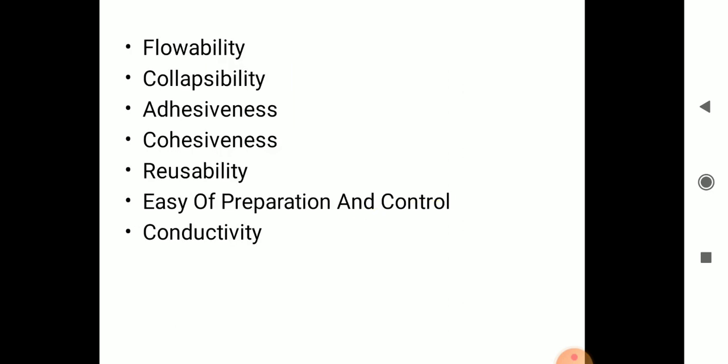Next is flowability. The sand should pack well and flow under load. Sand of low flowability may result in non-uniform hardness, soft mold, enlargement of the casting or roughness of the casting surface. This is flowability. Next one is collapsibility. The molding sand should also have collapsibility so that during the contraction of the solidified casting it does not provide any resistance, which may result in a crack in the casting. Besides this specific property, the molding material should be cheap, reusable and should have good thermal conductivity.